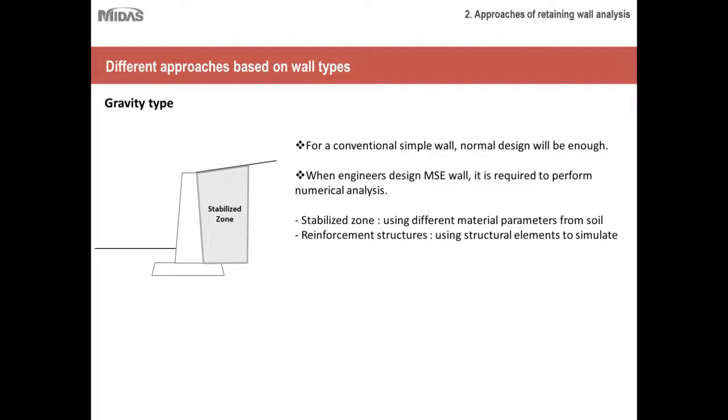But when engineers are dealing with the MSE wall, it is required to perform numerical analysis. And the important thing that you should consider in that is that the stabilized zone that I just talked about uses a different material property or parameter from the remaining soil, and sometimes they are reinforced structures, so you should model them and consider them using the structural elements.